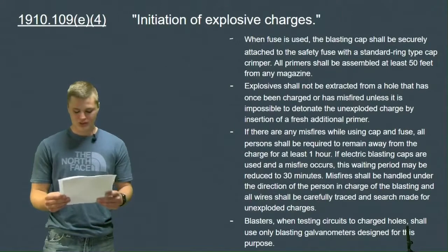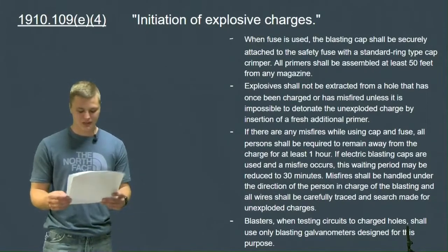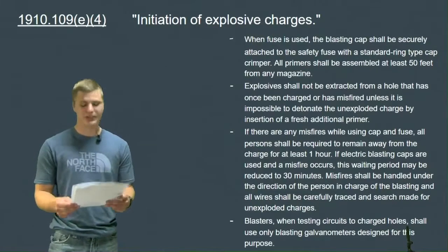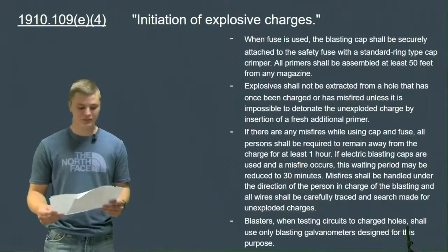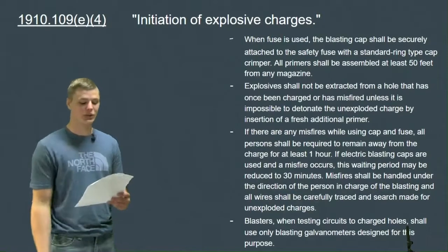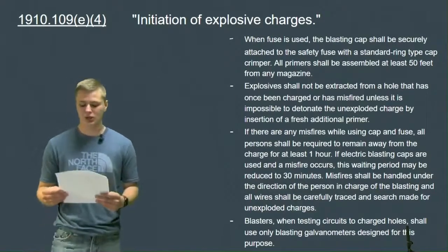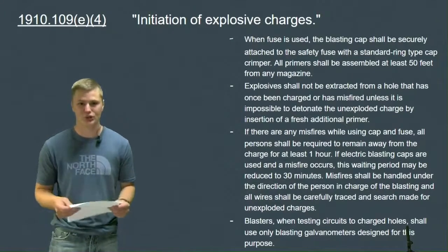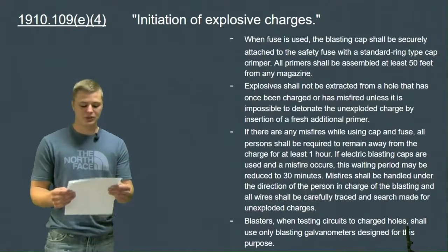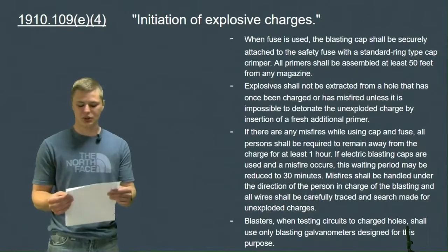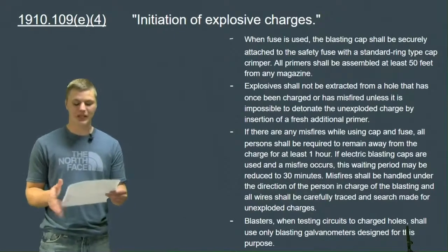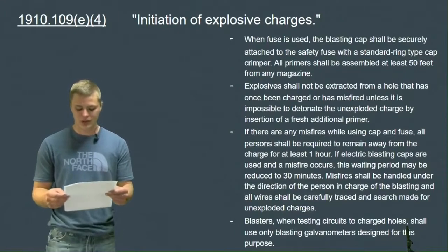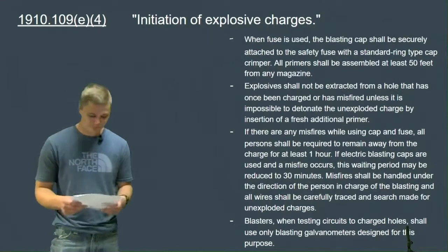But if you are using electric blasting caps and a misfire occurs, the waiting period is reduced to 30 minutes. Misfires shall be handled under the direction of the person in charge of the blasting, and all wires shall be traced back to the unexploded charges. Blasters, when testing circuits to charge holes, shall use only blasting galvanometers designed for this purpose.